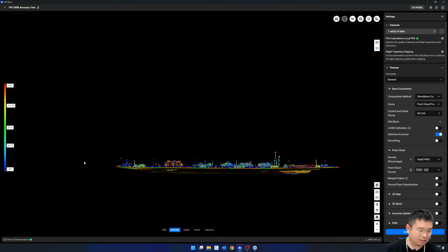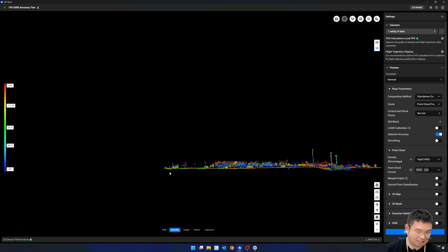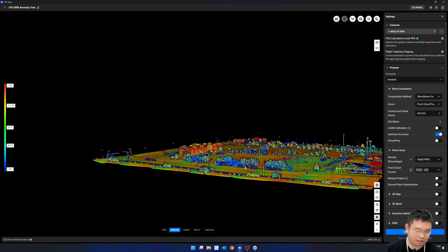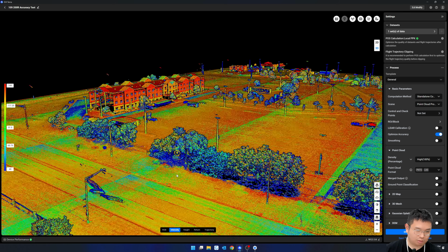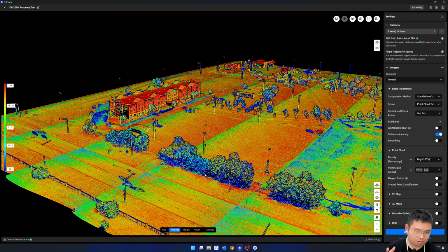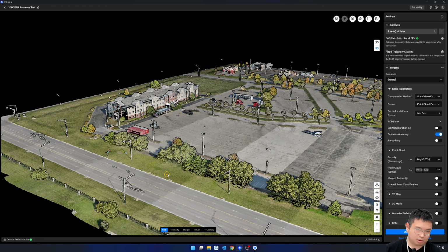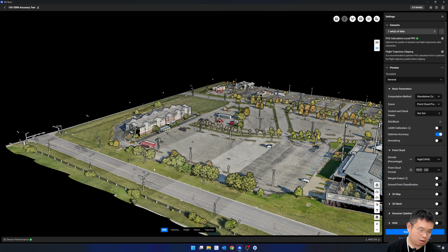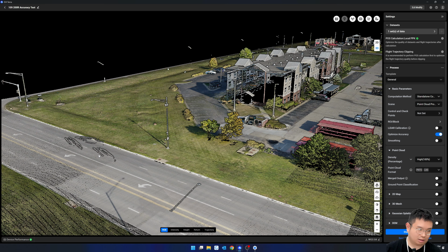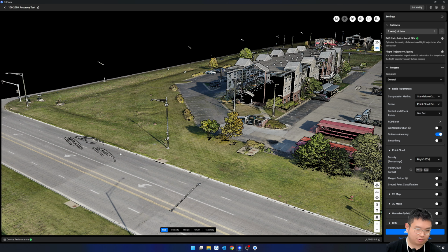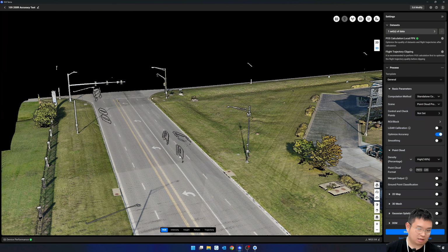And if you're capturing data in a high moisture environment or on a cloudy day, you may have noise points captured in the sky as well. These little noise points don't really affect much when you're doing a small scan, but it would be good to remove those, right? Because after all, this might cause the ground classification algorithm in Terra software to misclassify these objects as ground objects.